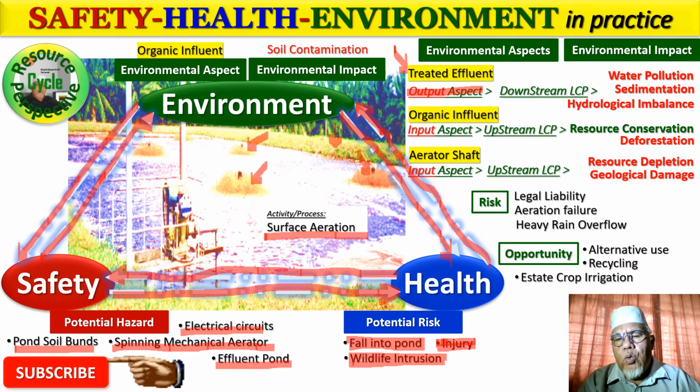It will flow into a water body. You've got organisms and other ecological inhabitants of the water body, and there will be interaction. And please remember, although it is a treated effluent, it still carries residual organic content because the BOD is still there. 50 to 100 milligram per liter is the BOD.